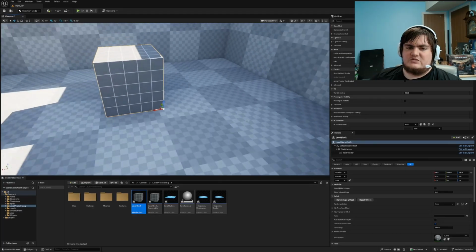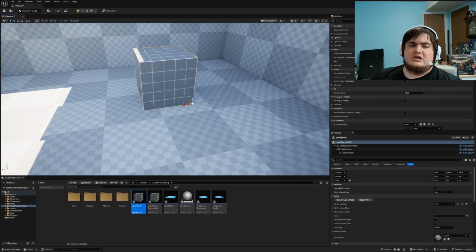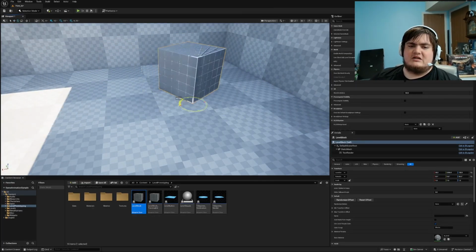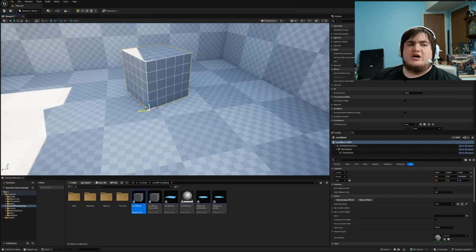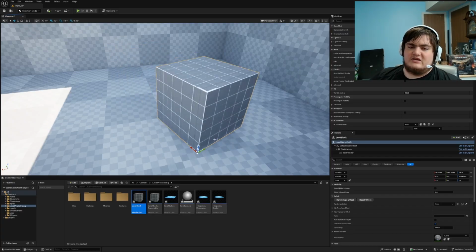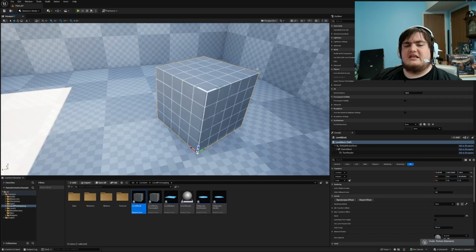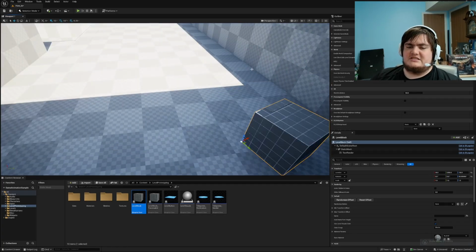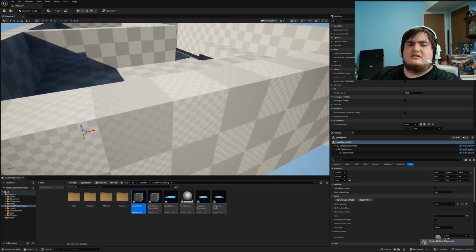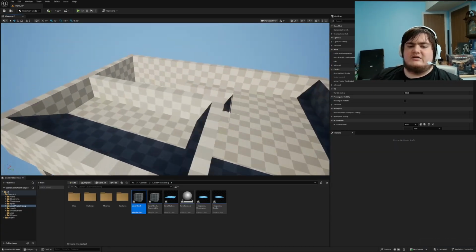So if I want to move it along this way, this is the world location. If I rotate it, it will automatically follow along this path. But if I move my mouse up here, I see this little spot right here. It looks like a little world. It says world space coordinate, so it moves based off the world. If I click that, it's based off the local. So now I can move it based off of where it's angled. That allows you to do multiple different little setups. So yeah, now from there we can easily go about and do other things.